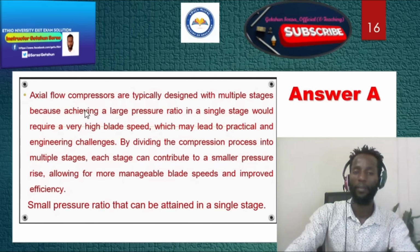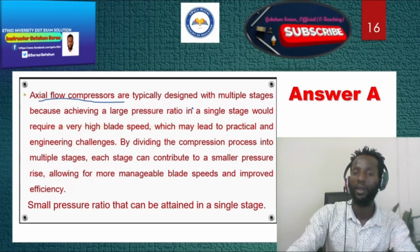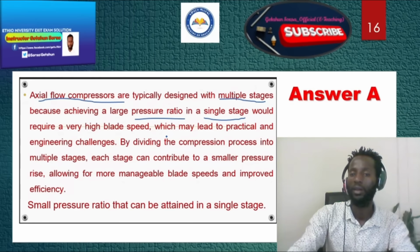To see the correct answer for this, axial flow compressors are typically designed with multiple stages because achieving a large pressure ratio in a single stage would require a very high blade speed, which may lead to practical and engineering challenges.